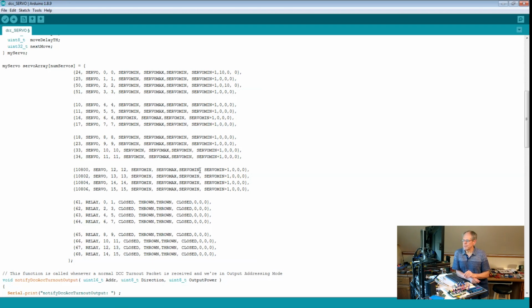Let's say we also have a motor that needs to be switched off, and we give it, let's say, 4 seconds in one direction and 2 seconds in the other direction, and then let's say the next one would be a 3-wire solenoid type that requires like 400 milliseconds for activation, and then the next one we can just copy that and say that's just like a quicker drive. So let's just go with the first 4. We have something for testing, and everything else we leave at 0. That means they stay on forever, which means one of the relays is always on. Okay, so that would be the definition. We already defined, now we have 24 drives in total.